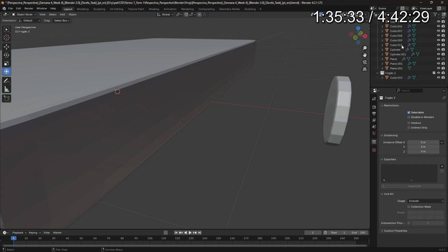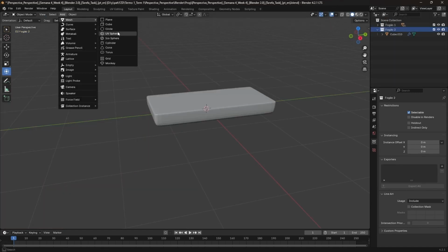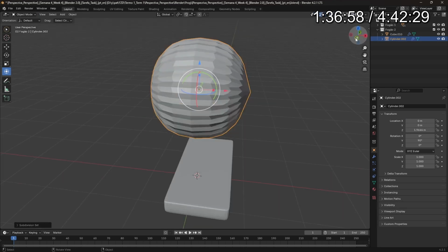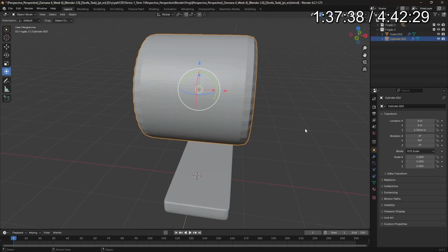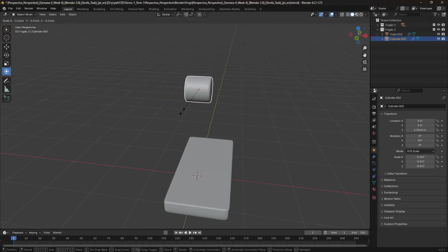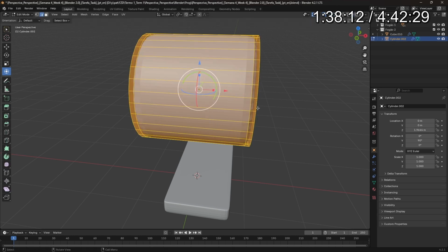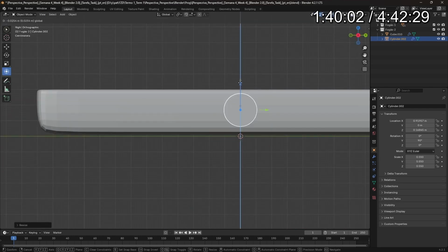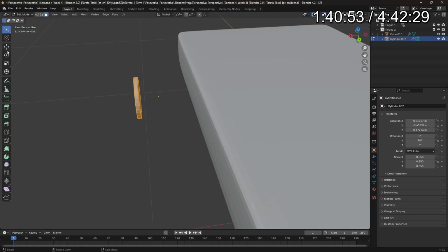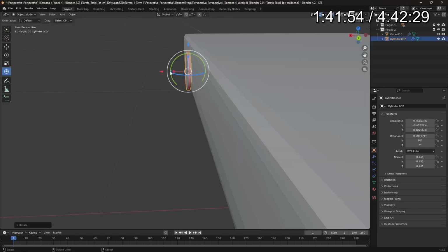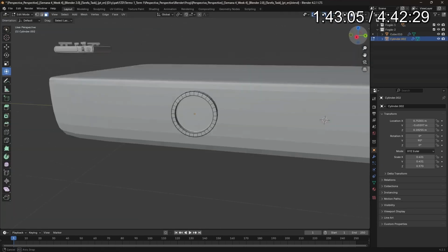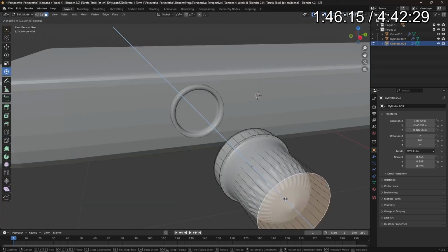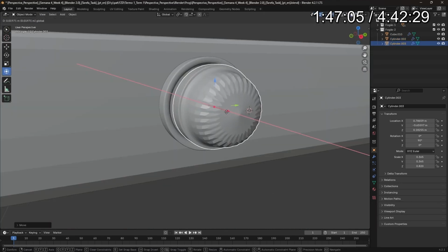After that, you can see that I just deleted all the things and added a cylinder, because with a cylinder it was easier to perform the same thing. So just applying the subdivision surface modifier, doing the bevel, selecting the face that I wanted, scaling it and inserting the face. This way I was able to do the thing that I wanted quickly, in a more efficient way. So I spent a little bit of time over there just refining it, as you can see.